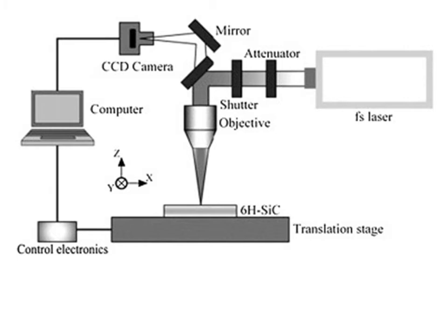So in order to adjust that power depending on the material that we want to process, you will have to use an attenuator. Attenuators are available at various capacities. It can reduce the power level of the laser which is passing through it to a specific ratio.